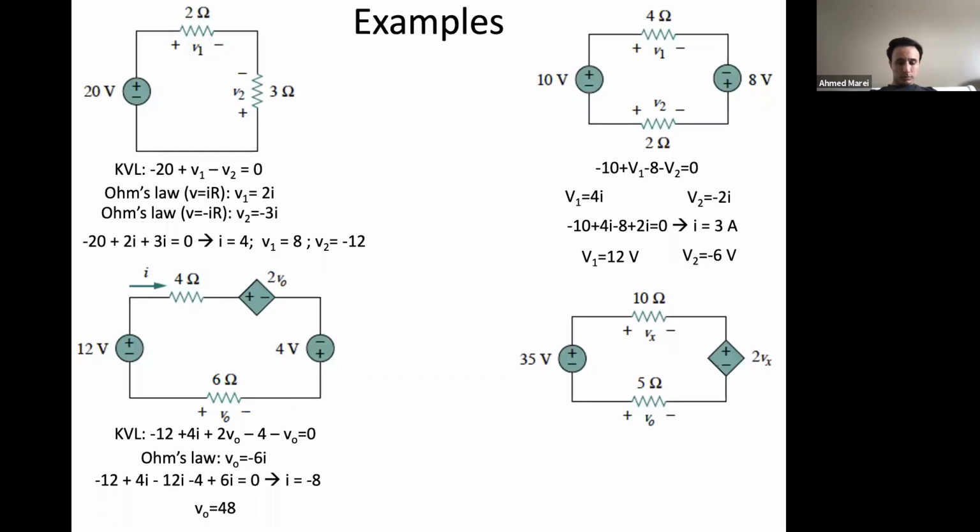All right. And then we have our fourth circuit on the page here. So who can help me with the KVL equation starting at the bottom? Why are the first voltage terms for each example negative? Because we're starting at the bottom left and we're going up. So we're hitting the negative end of the battery. So it's a voltage rise. Yeah. So same thing here. It's going to be negative 35 and then plus what?